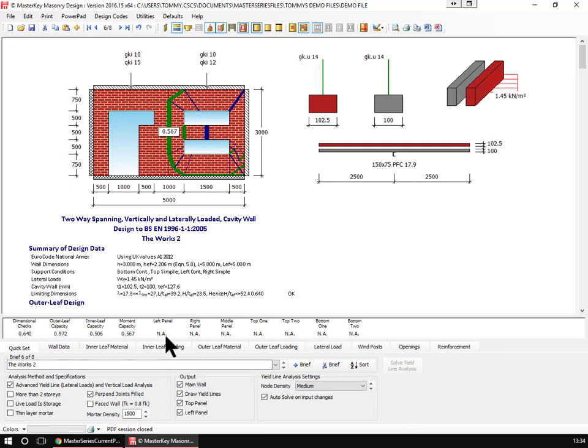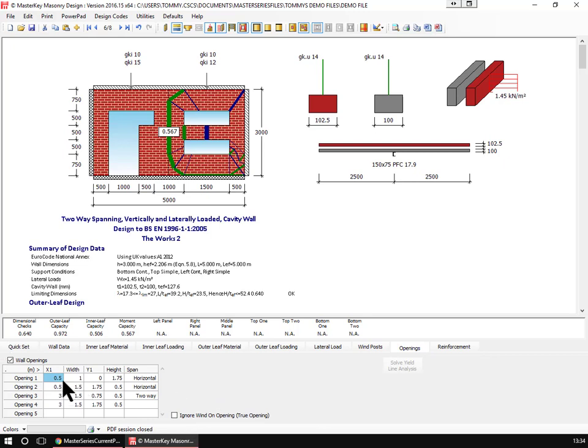So what have I done? First of all, let's look at the openings. I've stipulated 3 openings, in fact 4 openings, because this is an extension of that. So we've got this wider opening on top of this. So if I was to take this and say move it up from 7.5, come back here to 9.5, you should see that it moves up.